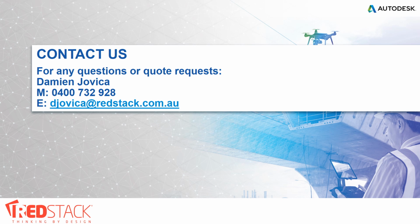I think they're under 30 odd grand, and they'll do a scan and photos. But if you've done a laser scan without photogrammetry and you've done photos, yeah, you could attach it in. It's like attaching multiple laser scans. As long as the coordinate system's accurate, you're going to get that.